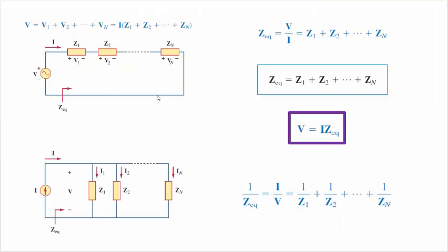So I have here just two generic circuits. One's a series circuit and one's a parallel circuit, and this is actually how you'll attack these problems. Every component, every element that you have in the circuit, and there's some elements in series, every single one of them has a voltage associated with it, and every single one of them has an impedance associated with it. If it's a purely real impedance, it's a resistor. If it's what we call a reactive impedance, then it's a capacitor or an inductor.